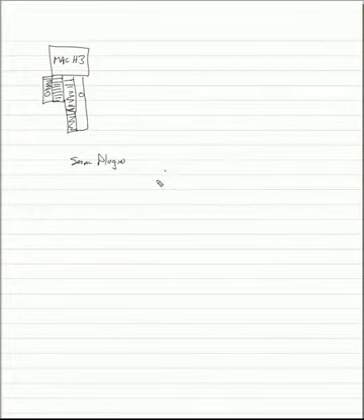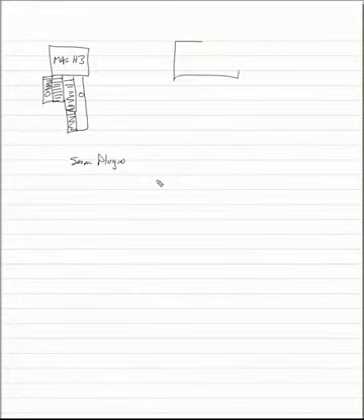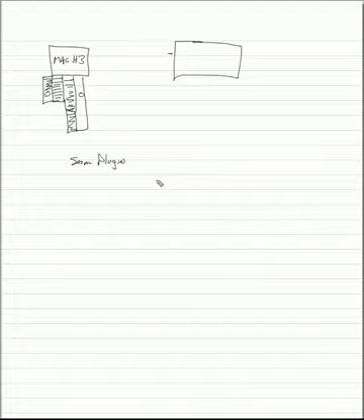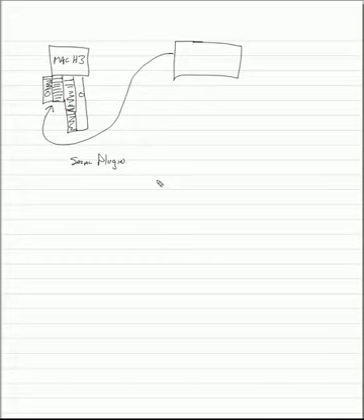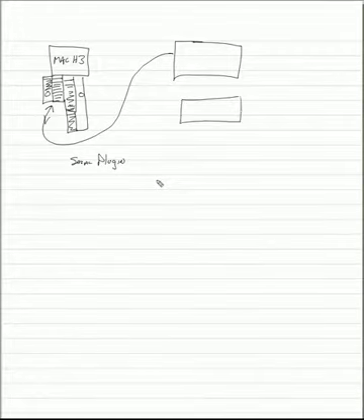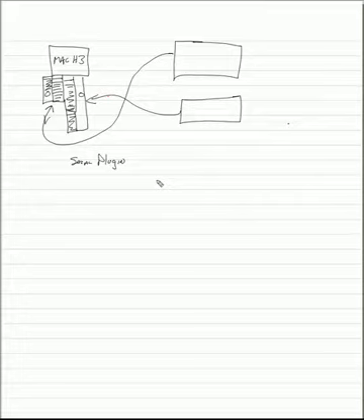The configuration of the buffers for serial plug-in ModBus are a little bit different. Remember that we have a PLC, which approximately 10 times a second, or whatever the refresh rate is set at, transfers data in and out of the serial ModBus area. TCP ModBus operates inside the TCP buffer area. Both of these are PLCs sending and returning data.